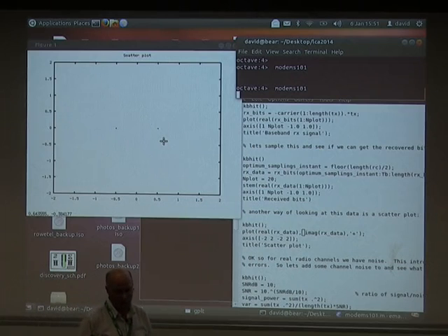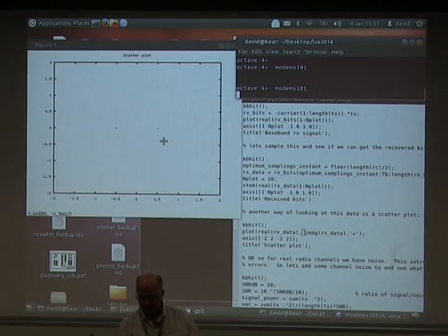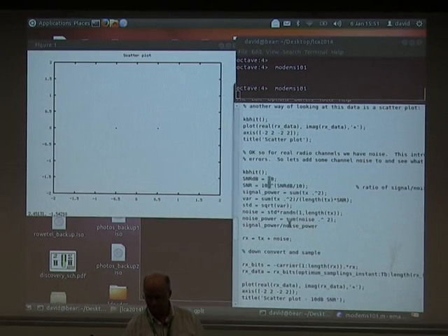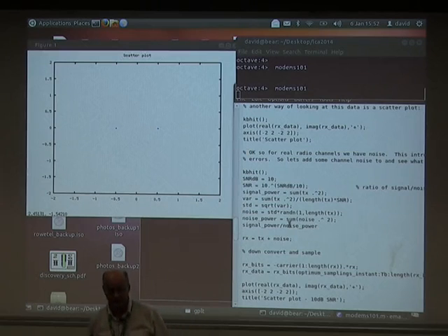You tend to draw quite a few of these sort of things. For modems that run, often we have a real-time display of this sort of thing to get a feel for the signal quality and how the modem's performing. So in a real world radio channel, the signals don't look quite as good. We have noise. When you get enough noise, it introduces a bit error.